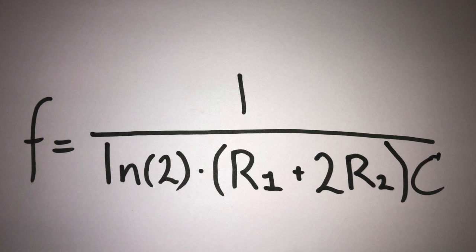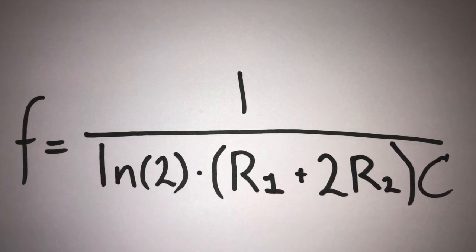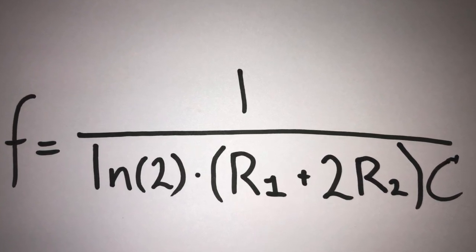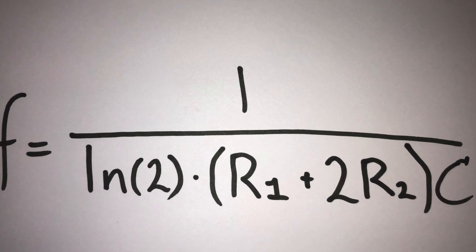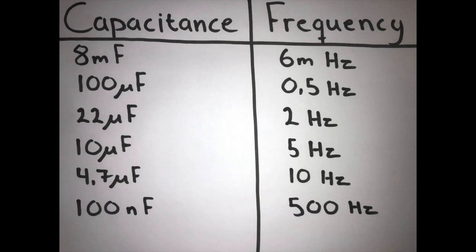The frequency of the 555 timer can be determined with this equation, which shows that for a larger capacitor the frequency will be lower. The 100 nanofarad capacitor produced such high frequency that the display didn't switch numbers but had all the segments lit up at the same time, showing a constant 8.